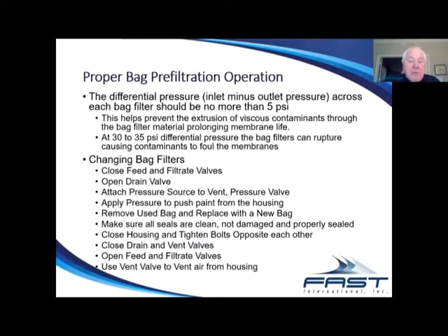Remove the bag and replace it with a new bag. Obviously, I always like to take a look at what's inside the bag. What do I see that's happening in there that should not be there? Are there large paint particles? Are there other things in there that should not be there? Is the bag showing indications of high pressure, or has it been ripped? And it gives you a little bit of input as to what's happening in the paint.